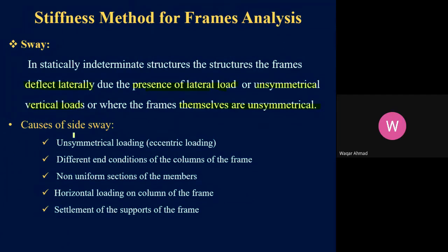Now let's summarize them again. The first cause is the unsymmetrical loading. Unsymmetrical loading means that there is some eccentricity present at the point where the load is applied. Load is not acting exactly at the middle of the member. So this causes lateral deflection.